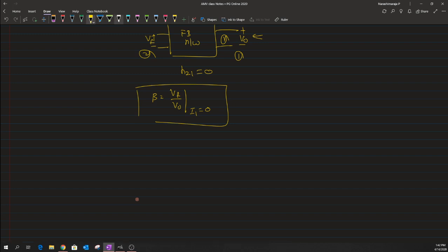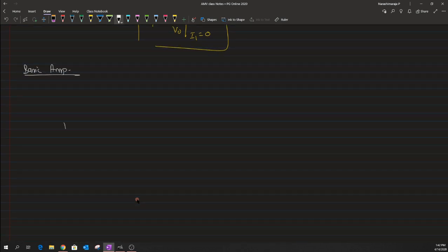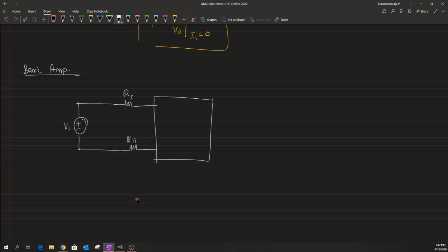So again let me draw this final circuit, which is the open loop or the basic amplifier circuit, which could be used to compute this Ri and R naught. This basic amplifier circuit will have an input voltage, along with the source resistance and the R11 parameter taken out from the feedback network, and it will also include the feedback network output component as well as RL.